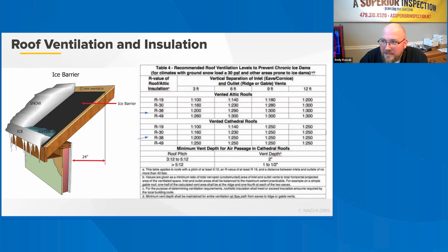Employing an unvented attic space may require designing the attic roof space as conditioned space, similar to that required when creating habitable space in the attic. There are several sources with more information on unvented attic designs. Traditional attic ventilation remains a cost-effective, though imperfect, solution for moisture control. In colder climates, roof ventilation serves to remove humidity and condensation from the roof attic space and helps to prevent the chronic formation of ice dams at the eaves.